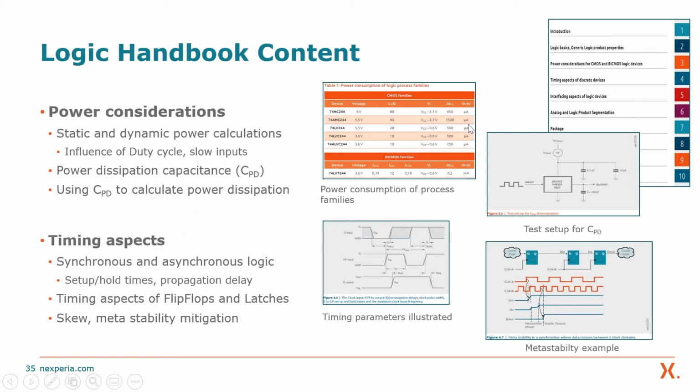The next important aspect is the timing. For timing, we cover the synchronous and asynchronous logic devices, and very important here are things like setup and hold times and propagation delays that we explain, and these are mainly valid for flip-flops and latches.